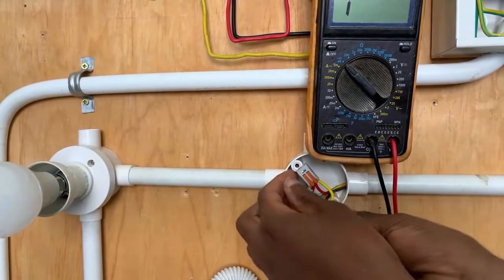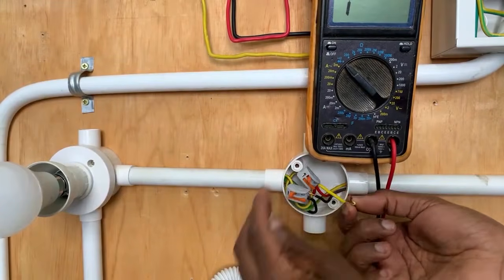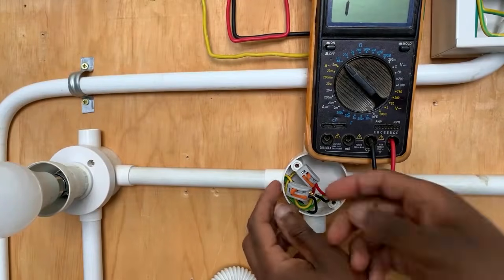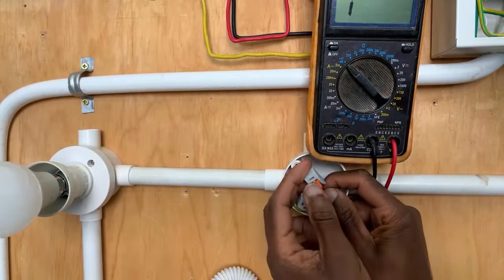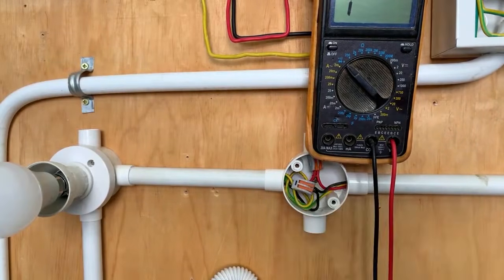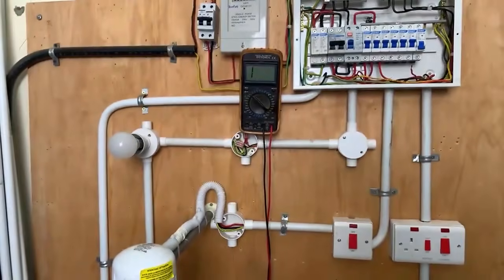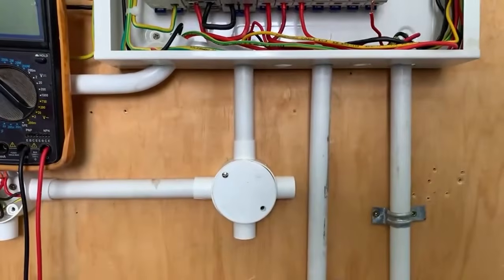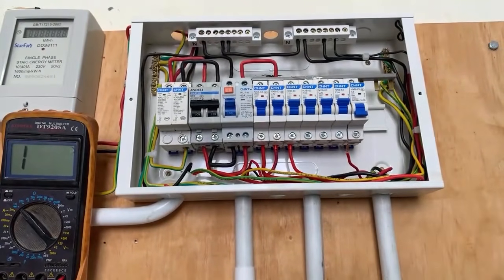So let us remove this short circuit by simply disconnecting our jumper wire that we had connected, that one, right? Short circuiting the line and the neutral. So we get it back like that. On this one, get it back. So there is no short circuiting between the neutral and the line. And then we come back here again and we record between the outputs, assuming that we are still troubleshooting the problem and solving.